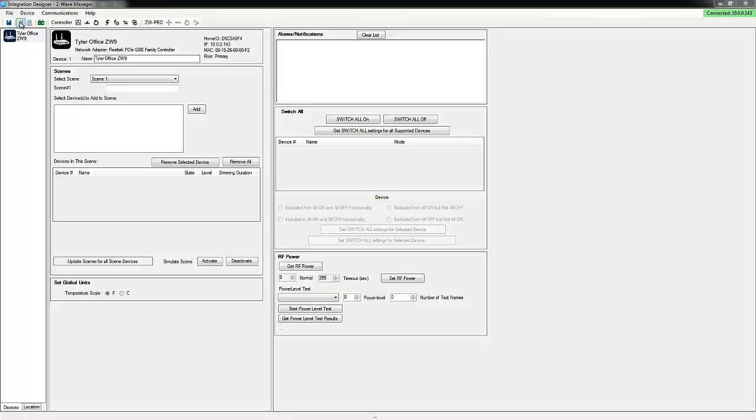This range is dependent on the device itself. For example, a door lock will have a smaller inclusion range, so only configuration devices nearest to it will recognize and connect to it, versus a light switch, which will have a larger inclusion range. For this reason, we have developed the ZW Pro, a USB-connected device that will help with the inclusion process of those devices that have shorter range, and thus not be able to be recognized by the ZW-9 on the initial edition. We will discuss how to use the ZW Pro shortly.